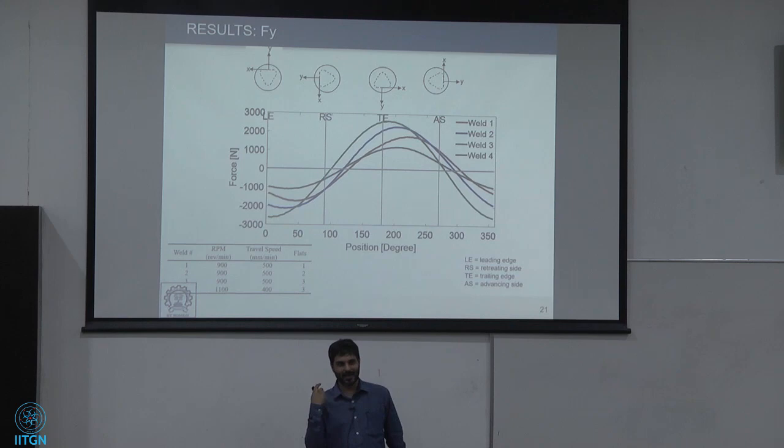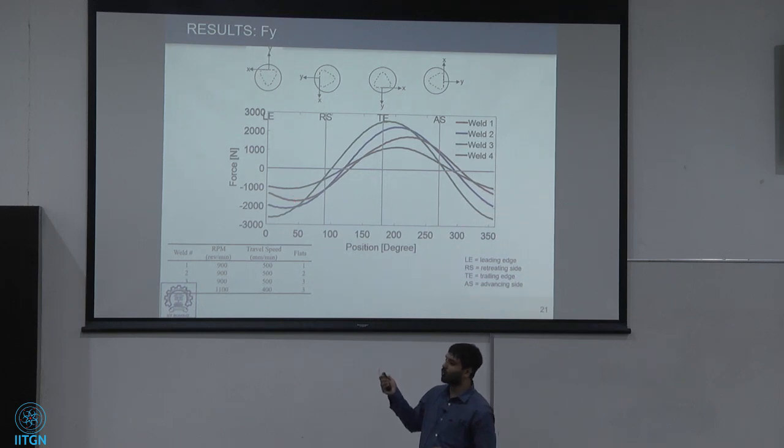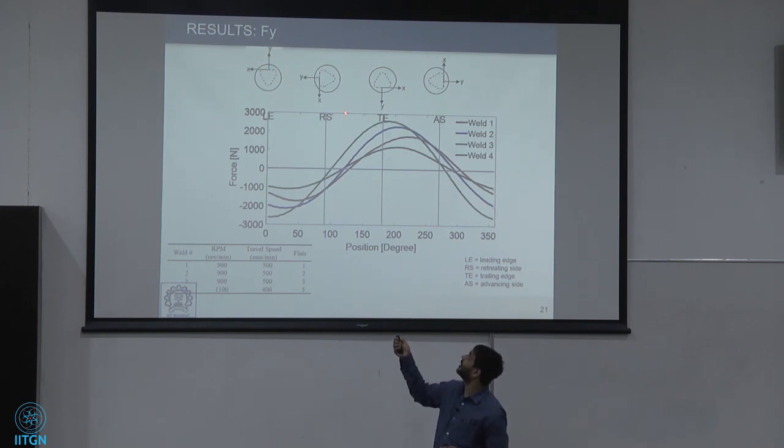Why? Because this again in some sense reflects that there is a cavity which is formed at the rear of the tool. Imagine if there is no cavity and there is a lot of material present at the back of the tool. Now the material which is moved by the pin has to push against the material which is present at the rear end of the tool.